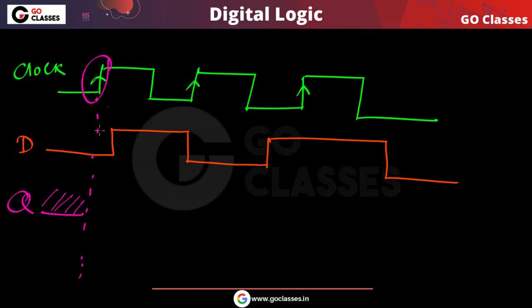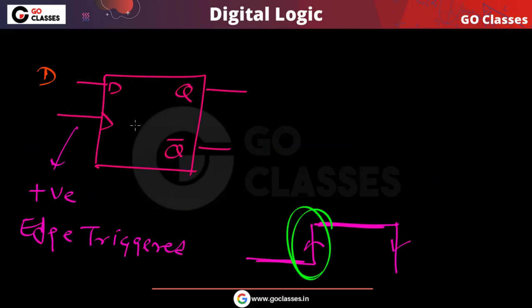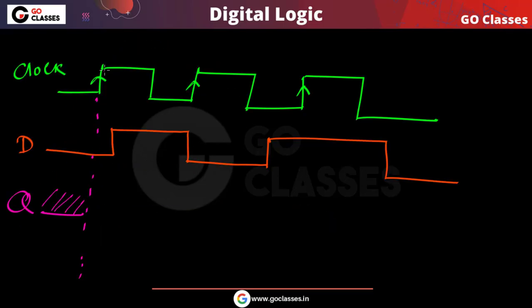Now you can notice this is the rising edge of the clock. So during the rising edge of the clock, this flip-flop will work, and I can say that Q will be equal to D. And because at this point of time you can notice D value is 0, that is the reason this Q will be 0 till the next rising edge.